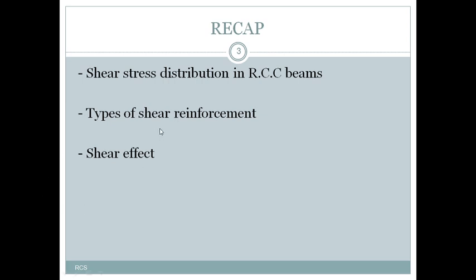Generally, vertical stirrups are provided around the tension reinforcement, and at the compression zone this stirrup will be hung, or tied with hanger bars. Generally these stirrups are provided with a diameter of 6 mm to 16 mm, and based on the intensity of shear force we choose what type of vertical stirrup reinforcement is used, say single legged, double legged, or multi legged, and so on.